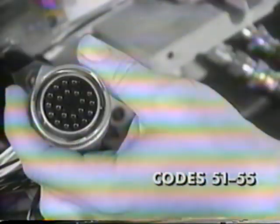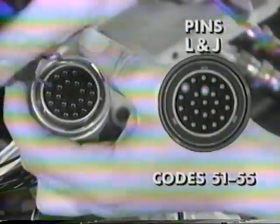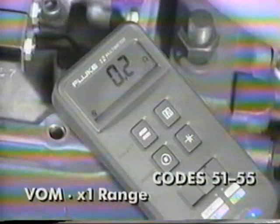You want to check the harness for abrasions too, because sometimes part of the harness gets pinched under the shift bar cover and can cause a short. Now, check the continuity. On the auto shifter harness connector, probe the appropriate pins. For code 52, it's L and J. The resistance should be less than 0.3 ohms or continuity.